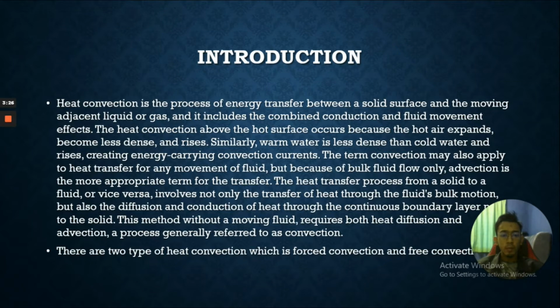The term convection may also apply to heat transfer for any movement of fluid, but because of bulk fluid flow only, advection is the more appropriate term for transfer. The heat transfer process from a solid to a fluid or vice versa involves not only the transfer of heat through the fluid bulk motion but also diffusion and conduction of heat through the continuous boundary layer, a process generally referred to as convection.